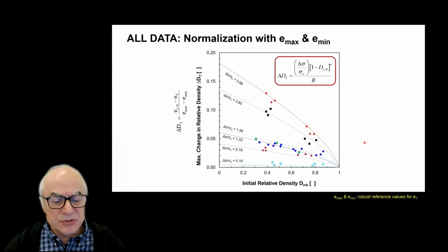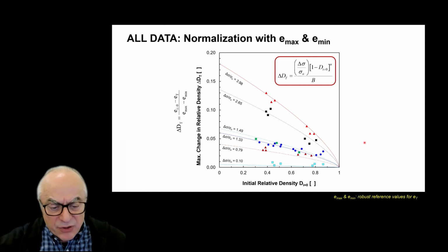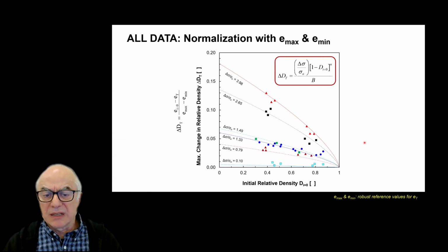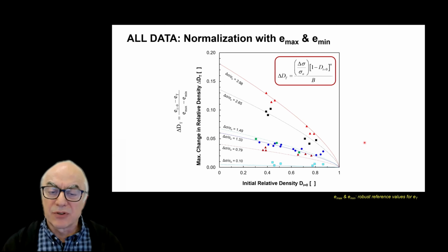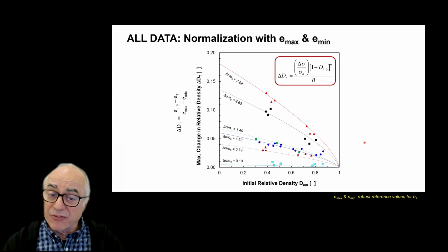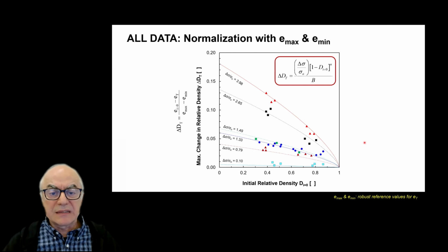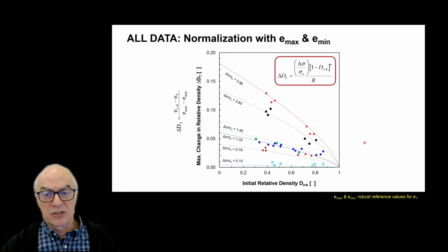So the terminal void ratio is more complex than, for example, critical state. Each material and process will have its own terminal void ratio. Critical state falls into this overall summary, and critical state represents the terminal void ratios under monotonic shear.